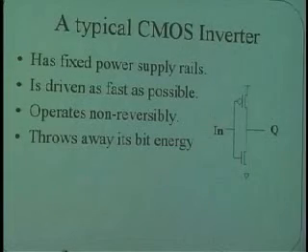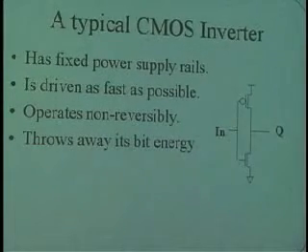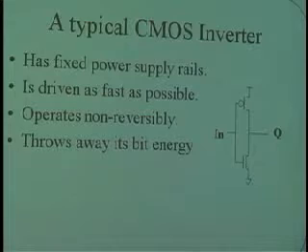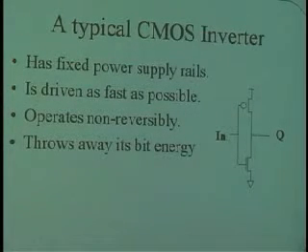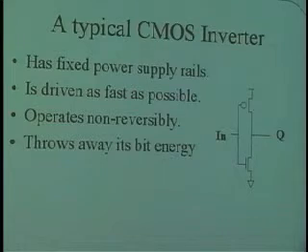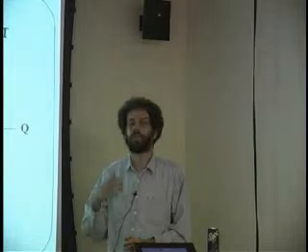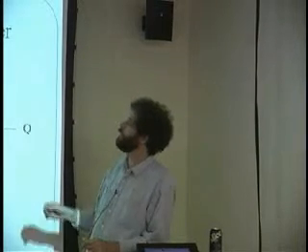On the other hand, you could have a flywheel, for instance, and some kind of automatic transmission mechanism in order to slow the car down by extracting the energy in the wheels and spinning up some flywheel at the same time. And at the end, when you came to a stop, the flywheel would be going at some speed and you'd have some energy there. Or you can use the motor as a generator and you could charge the battery as you slow down. This thing works the same way.